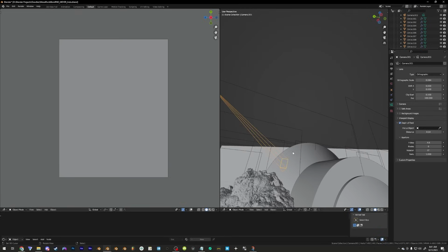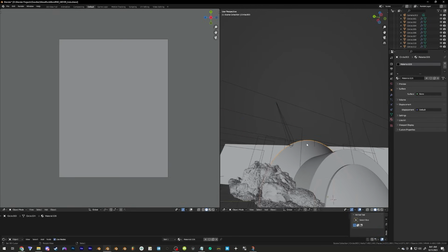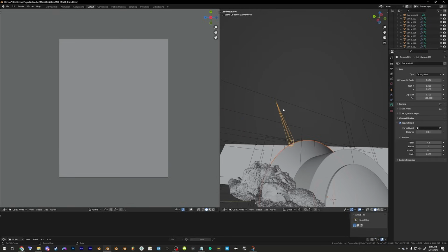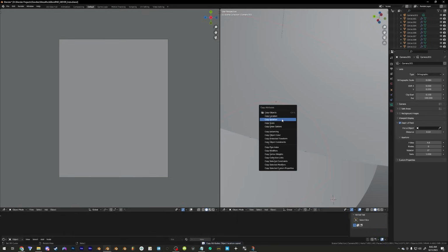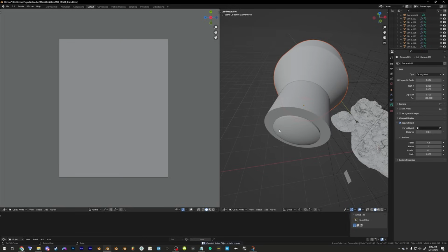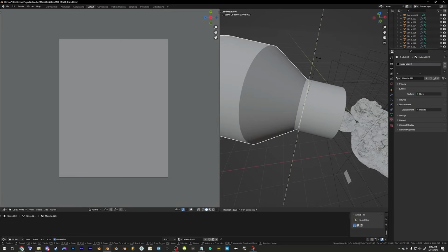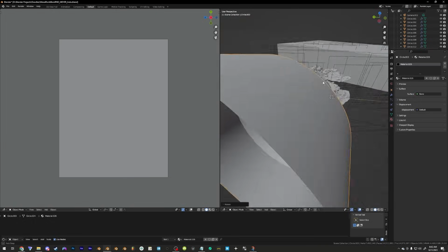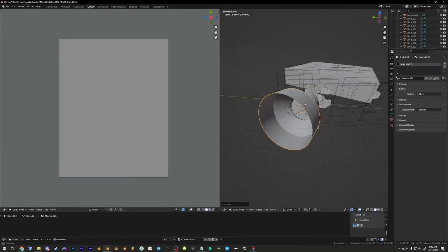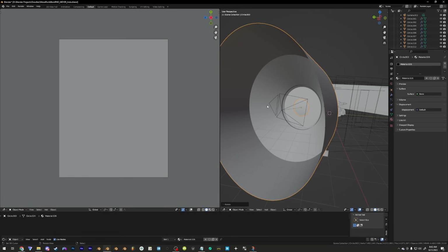This camera is upside down because there was already a lens attached to it, but most of the time you would not have the lens upside down, or camera upside down. I'm going to copy the location, copy the rotation. That way, it is aligned with it. It is currently offset by 90 degrees. All we have to do is R, Y, Y, 90 degrees, negative, enter. And we can look at our orthographic camera right here. It is currently offset. It's not directly upside down. This is when we go R, X, X. Sorry, I'm so brain dead. 90 degrees, enter.